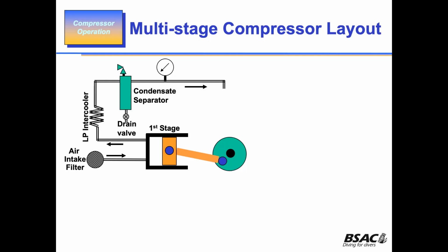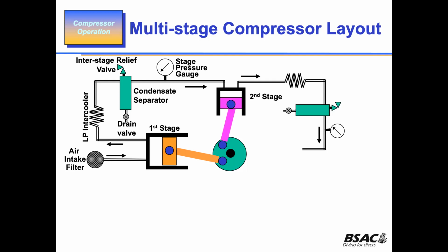So that's your first stage. That first stage takes your air from atmospheric up to the pressure of the first stage, which is probably around about 5 or 6 bar. It's not very, very high on the first stage. Now we push the air into the second stage cylinder.